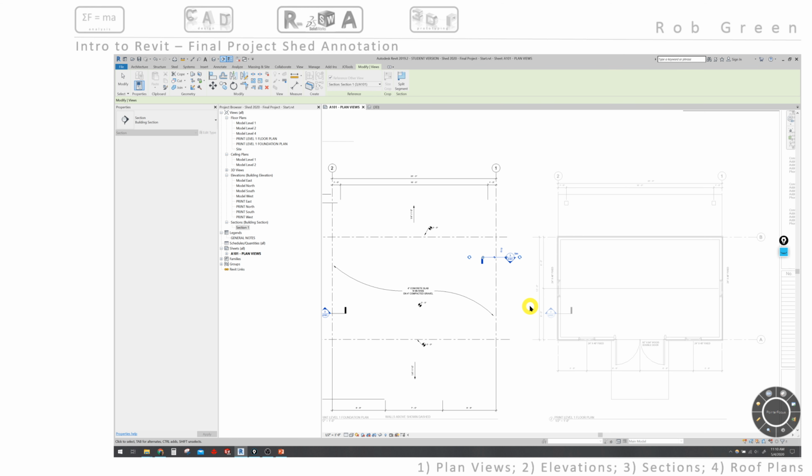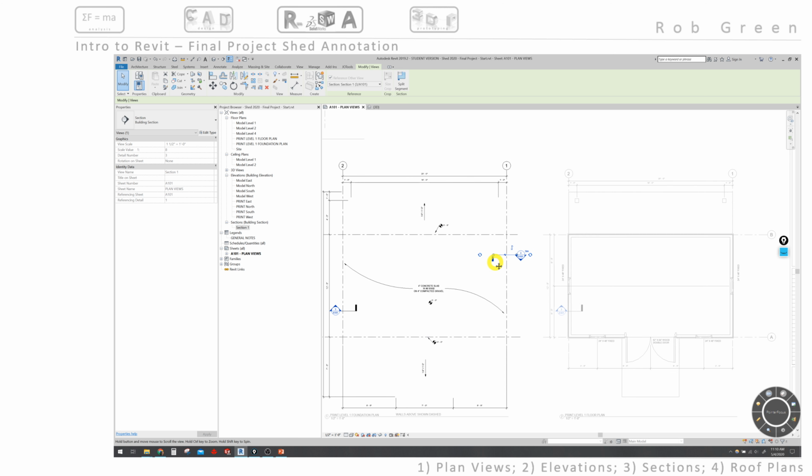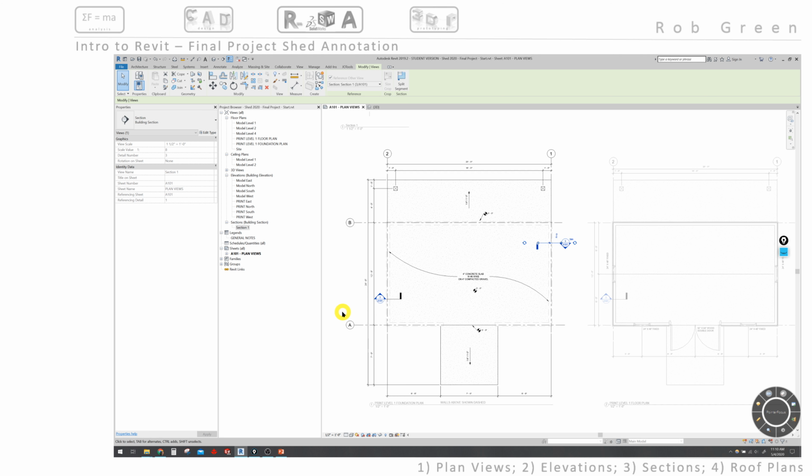So what I want to highlight is that in the section view, I want the orientation to be correct to the actual view itself. So if I am standing looking down, the outside of the building is on the left. And if I am over in this area and standing looking toward the area, the outside of the building is on the left.